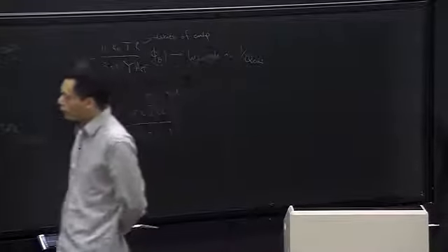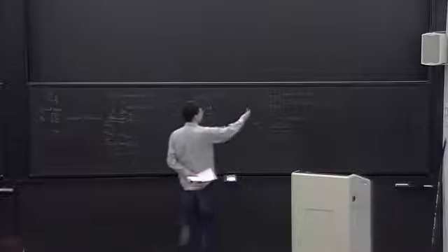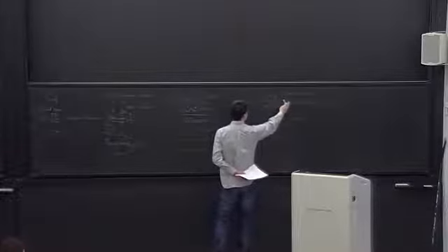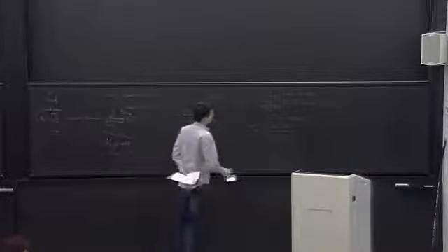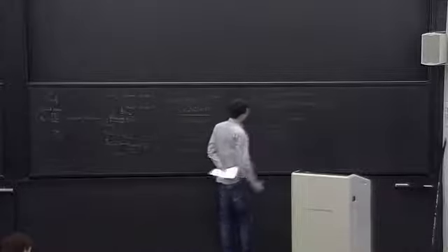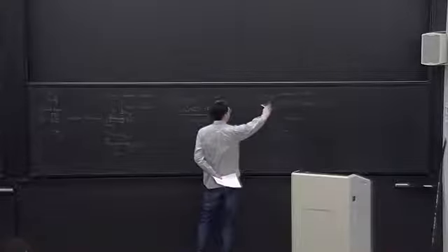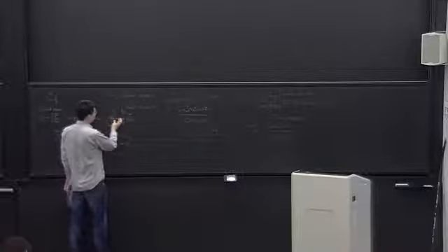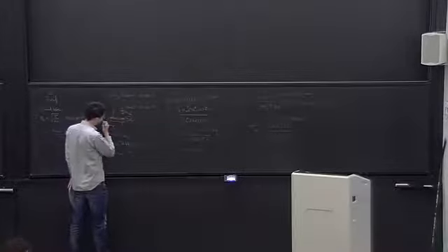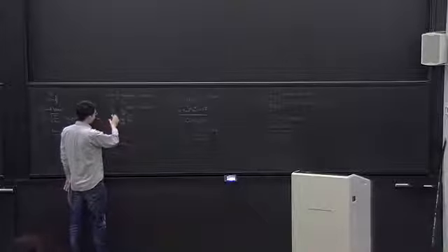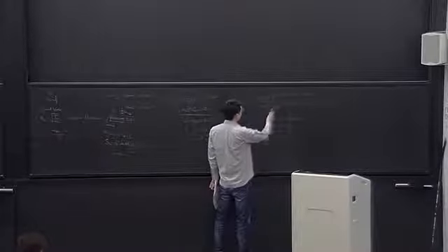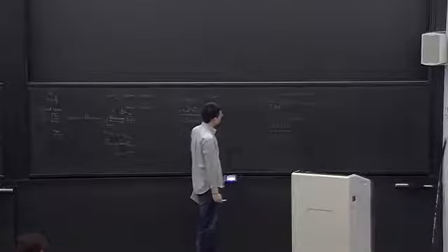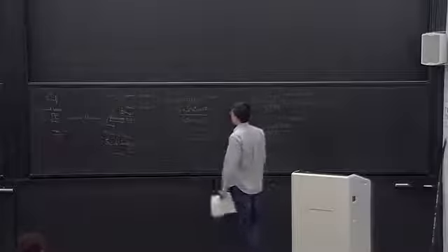So according to the fluctuation dissipation theorem, the spectral density of the fluctuating force is proportional to k_B T. That's why there is a k_B T. And it's proportional to the loss, which is proportional to 1 over quality factor. And because it's a force, and I want to compute the displacement, the displacement is basically force over Young's modulus. The softer the substrate is, the more bending there will be, right? So it's inversely proportional to that, and then it's averaged over the beam profile, because it's a beam averaged quantity.